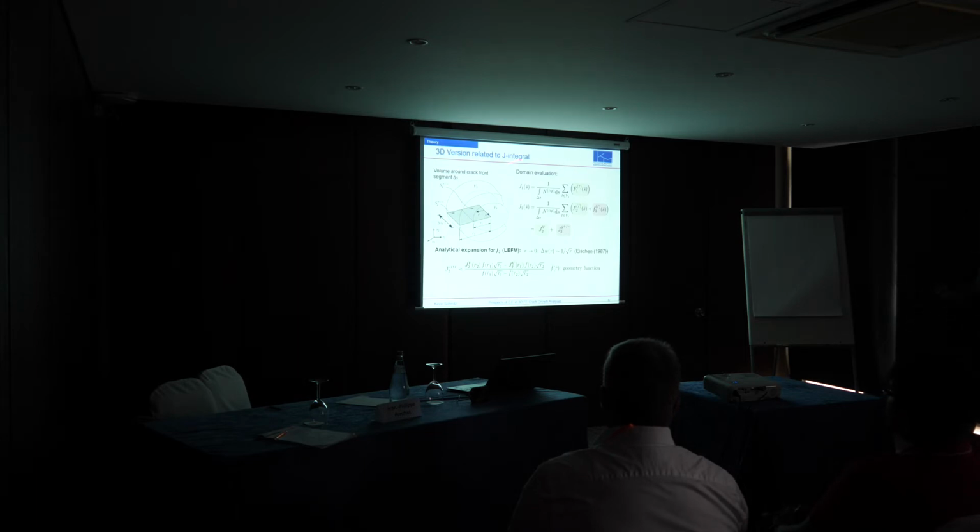So what we simply did is we took the knowledge that we have about the fields that are involved in the calculation of J2 and did a kind of analytical extension for J2 in the case of linear elastic fracture mechanics. We put in our knowledge about fields, do some maths, calculate some integrals, and this results in an extrapolation formulation for the value of J2 that we can now calculate only from knowledge of the geometry and from those volume contribution configurational forces, the forces that we want to calculate.